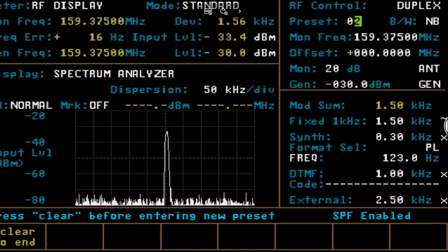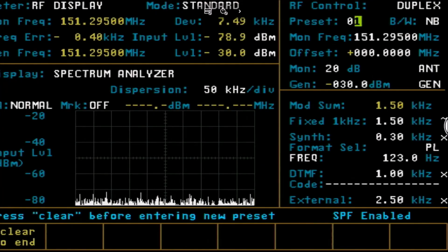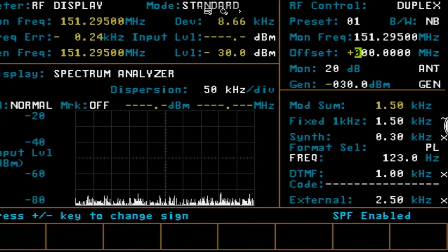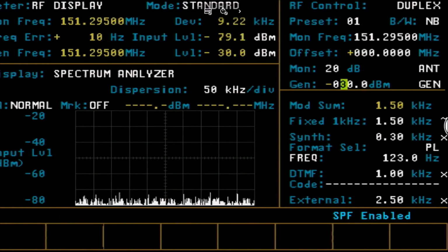Now let's go ahead and flip frequencies to the other side and confirm that we get complete rejection on that. So let me change the frequency there, and now we've come back, and you'll notice the signal is completely gone. And if I come down, I can actually increase my signal level here all the way to 0, and you still can't see it at all. It's probably got 70, 80 plus dB attenuation. They're really sharp notches. So we're completely good to go with that.